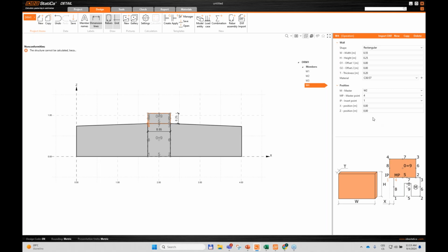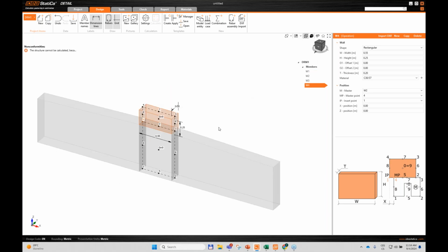So that's it. Now I need to set some thickness. As I said, it's a 2D solution, but you can still display how the structure would look like in 3D. And it's a good thing when you want to check if you set the right thickness, for example, because when you set calculation of self weight, it's regarding the volume. So it's good to know that it's correct. And see, I didn't change it properly, so I can do it now.